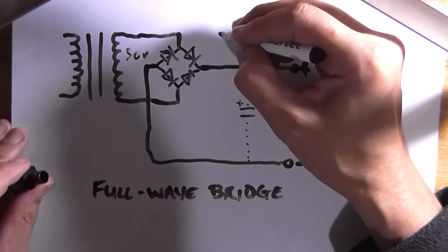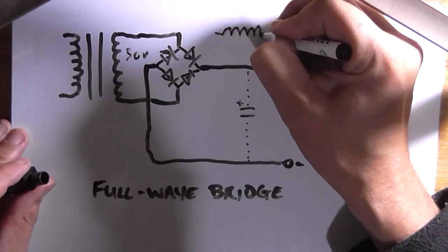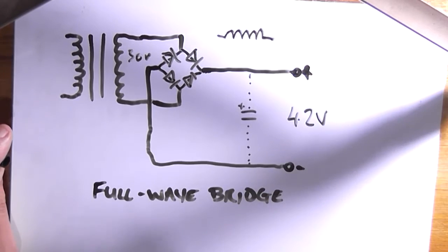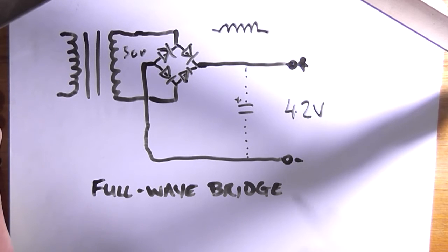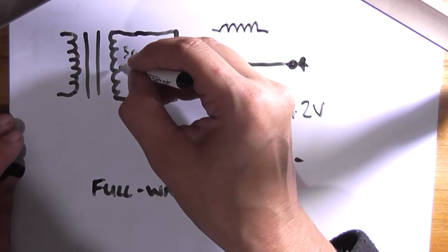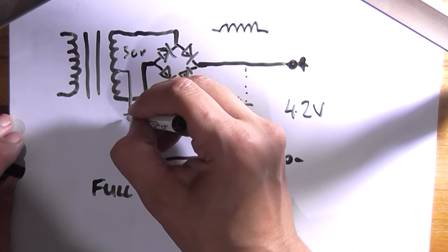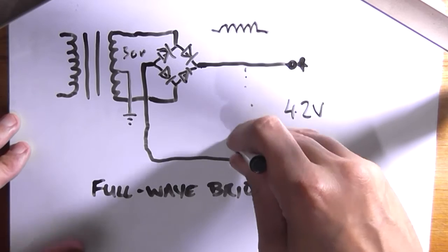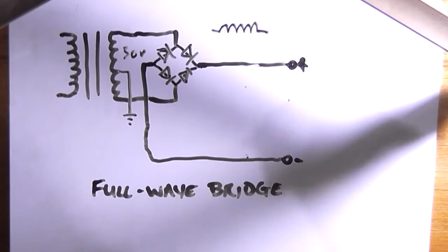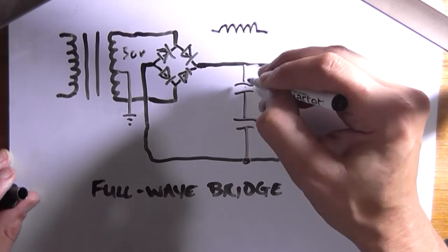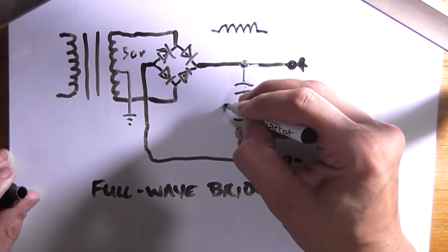And we're going to see the same exact signal on our oscilloscope here without a filter cap, because it's full wave. It still works the same way as the last circuit, and that's as basic as you need to understand about it without getting into a lot of engineering details. So you can actually use the center tap to form a 0 volt and turn this power supply into a bipolar one by adding two filter capacitors in series with each other.